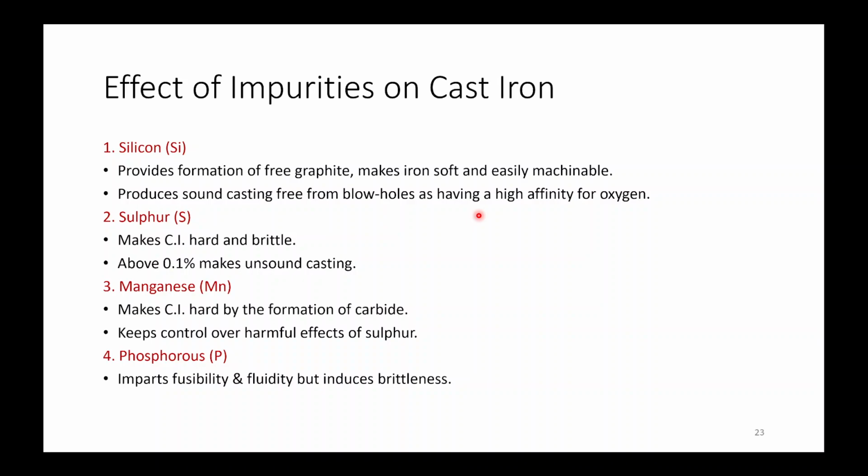And if there is sulfur, it makes cast iron hard and brittle. Above 0.1% it makes unsound castings.